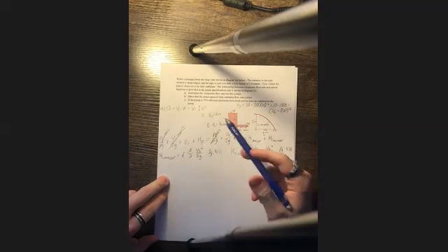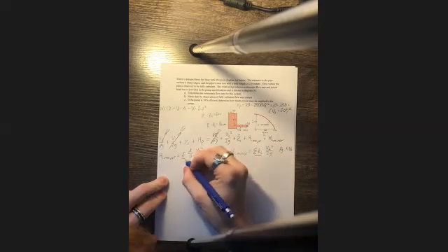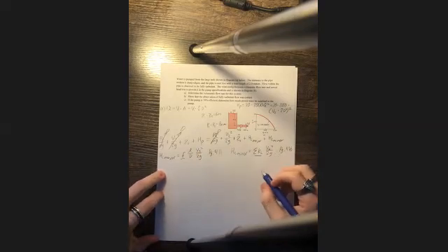So the whole point of doing Bernoulli's equation is we're trying to find velocity 2 at the exit so that we can solve for the volumetric flow rate of the system. In order to do that, we can only have one unknown. Right now we have 3. So we need to solve for both the friction factor and the sum of the loss coefficients. So first, we're going to solve for the friction factor.